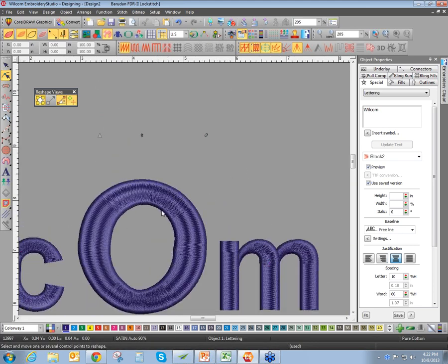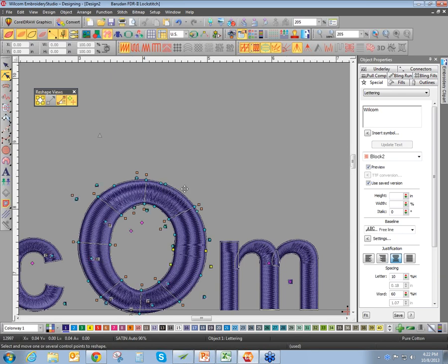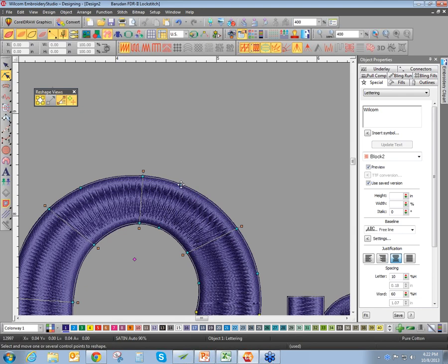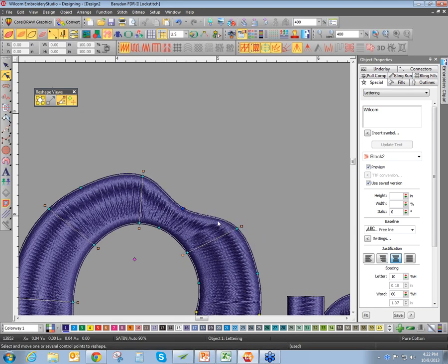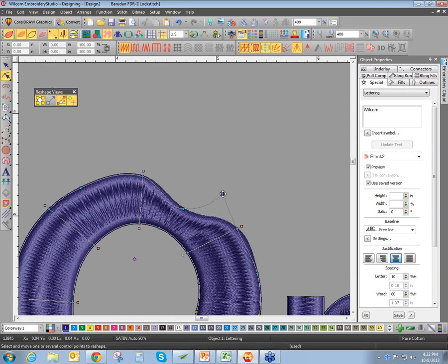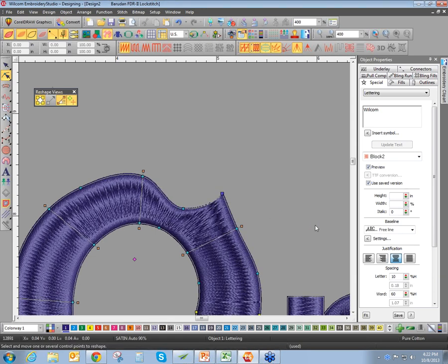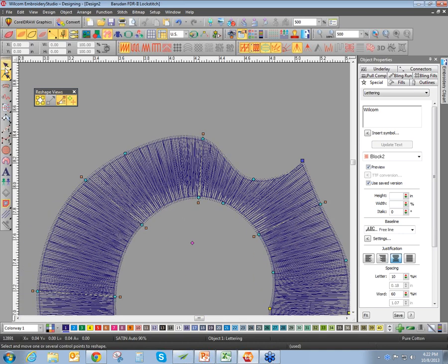If I wanted to do some node edit on this particular letter, really easy, again, real-time. Our circular points, or circles, would represent the curvature node or curvature outline. I can easily insert a square node by simply left-clicking, which would indicate a corner point. If you also notice, we have the protractor degree of the stitch angles, which, again, can be changed real-time.